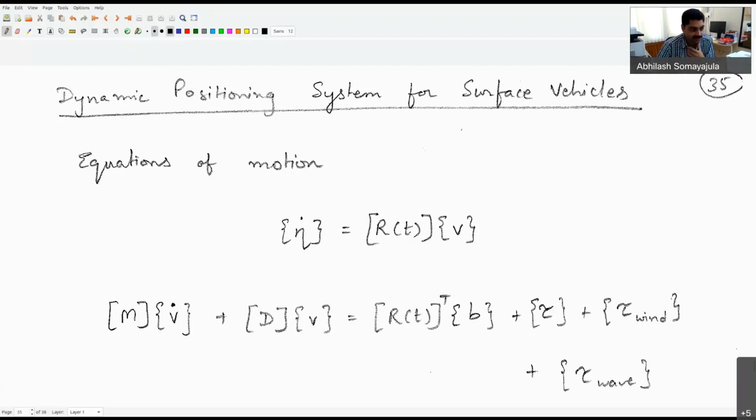All right. So what we are going to take a last look at in terms of the control system is, for a dynamic positioning system, how does the dynamics look? Because we know that in this case, we have a bias term which is trying to account for these environmental disturbances. How do we take care of that? Nothing new per se, but the dynamics looks slightly different, although it's exactly the same format as what we have seen before.